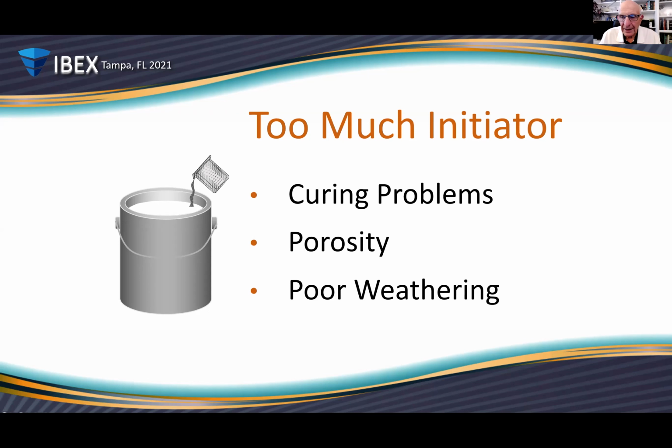One of the things that we kind of have fun with the students in the IRIS Composites Technology program is we go to a boat show, typically the Newport, Rhode Island boat show, which we just did last week. And they have assignments, like identify the size of the sanding block that was used to make the plug, to make the mold, to make the hull that we're standing there looking at. And you can identify on some hulls whether they used a long block or a short block because you can see the segments around the hull. That's one little fun thing.